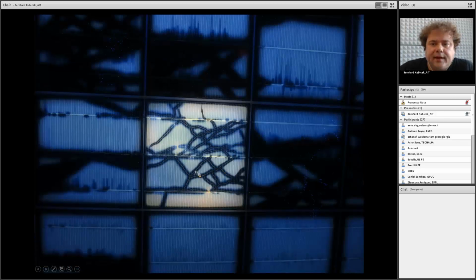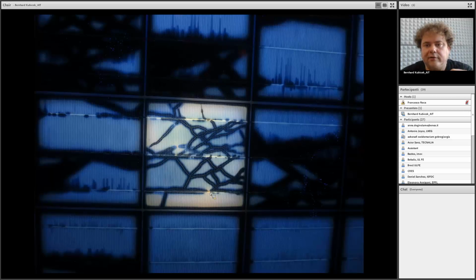What you see here is a hotspot cell that even has visible brown. So it was really in the field for a long time, was getting really hot, and the cell became brown. There are some short circuits here where you see even the oxidation of the cell surface and so on. And this cell is remarkably brighter than the other cells, because here you also have this red spectral range where you have the thermal damage. And if it's seemingly warm, it improves the production of these fluorescent molecules.